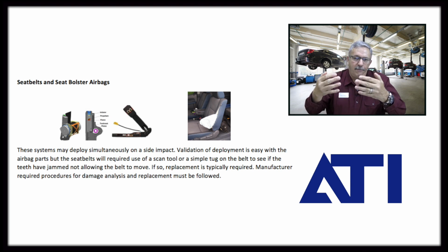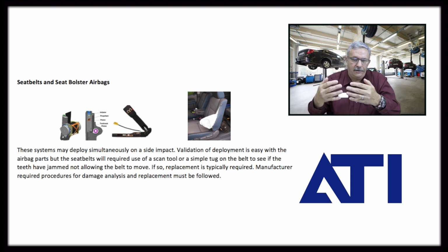It's made in a herringbone tweed for a reason. It's to move the strength from one side of the belt to the other. If one side of the belt is stretched, it will cause it to have that bow in it. So it's important to check to make sure that you don't see that. If you do, the belt has to be replaced.